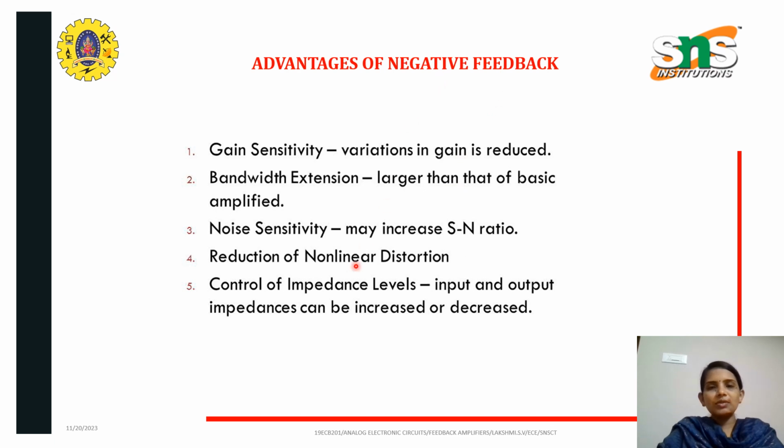Advantages of negative feedback are that the gain sensitivity, that is the variation in gain, can be reduced. Then bandwidth extension, noise sensitivity, reduction of nonlinear distortion, and we can control the impedance level. That is, the input and output impedances can be increased or decreased.